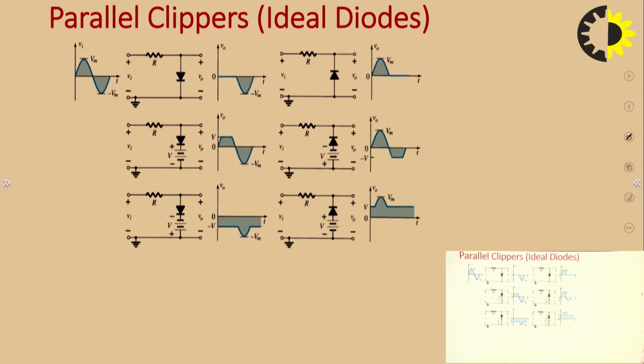So in this way we have again these six circuits. You can practice all these questions and solve all of them. Take a note of this, make two cases, and then the process is to find out where the diode is forward biased and where the diode is reverse biased, and then make the cases, case 1, case 2, make the circuit, and then apply Kirchhoff's voltage law, and then find out the answers for the two cases, case 1 and case 2, and draw the final output waveform.